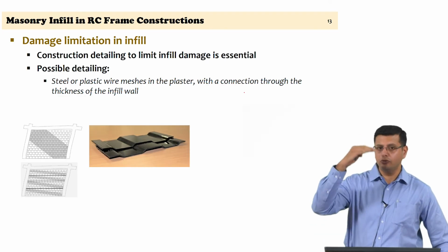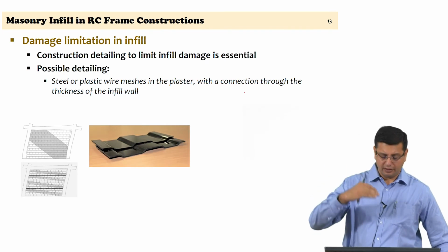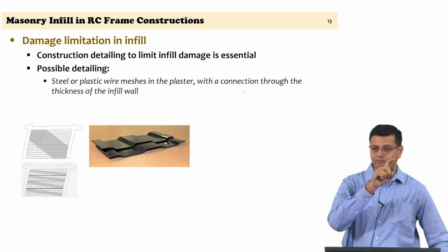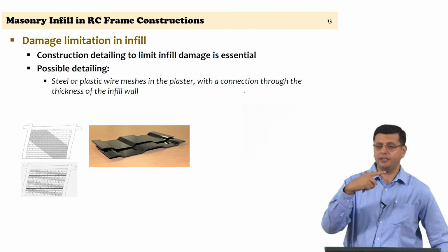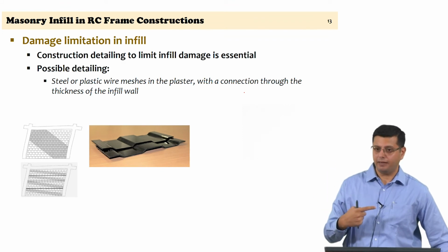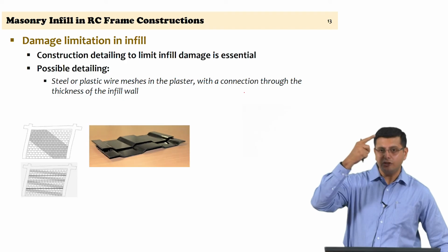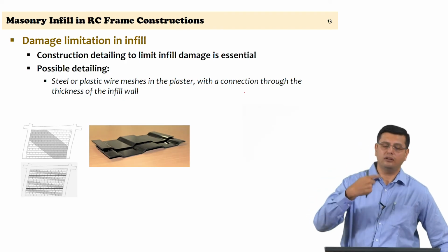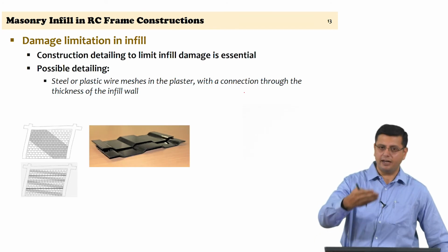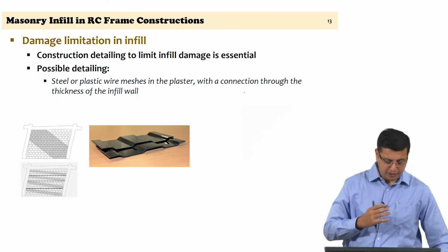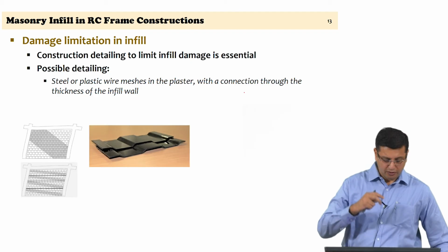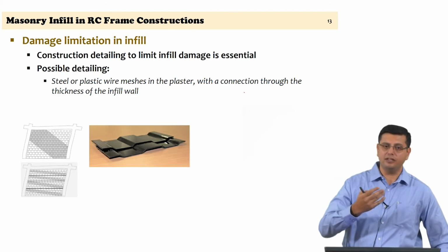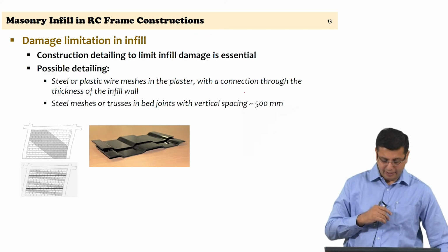Basically, what it is going to do is the panel is now divided into smaller sub panels within which the strut will develop. So, each of those have to fail to reach the ultimate limit state and for further expulsion to occur. So, by splitting these into sub panels, the capacity of the infill also can be enhanced.